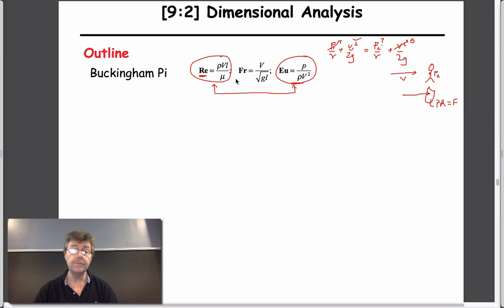The Froude number is used to be able to define behaviors where we have free surface flows. And so we've always looked at the idea of, for a different reason, our fireboat being dragged through water. So where you have a free surface, and typically where you develop a wave, a bow wave, and a wake behind you. A bow wave elevates it, so you can imagine that as you push a boat through water and you create a hump in front of you, which you really have to climb over, the boat becomes less and less efficient. And so this is where gravity is the main force that's driving this flow, right?